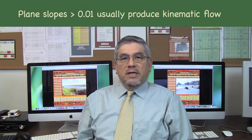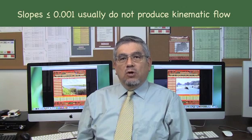Experience shows that plane slopes greater than or equal to 0.01 usually produce kinematic flow. Conversely, slopes less than or equal to 0.001 usually do not produce kinematic flow. That is, they are either diffusive or dynamic.